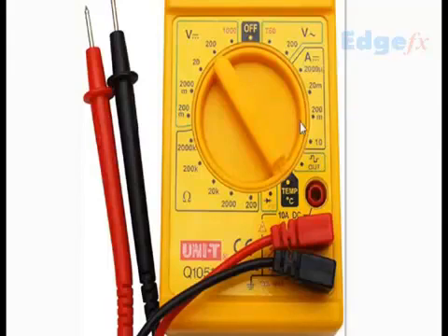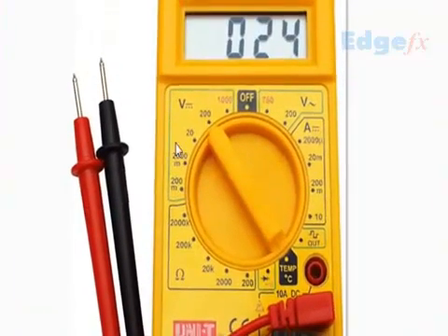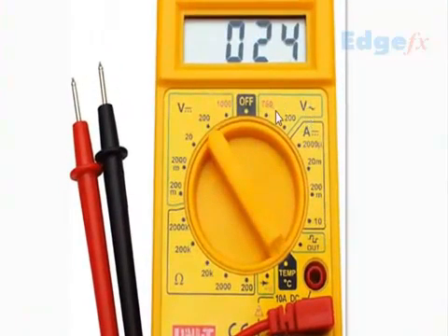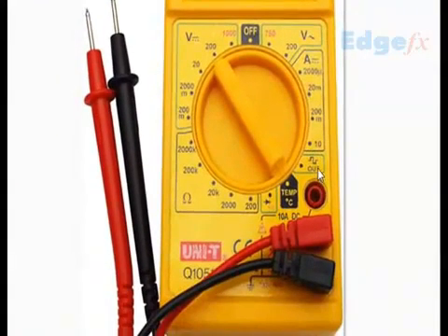This is a multimeter, and it has the provision of measuring DC voltage, AC voltage, and DC current, and some signal can also be drawn out of this. It also measures temperature with a temperature sensor, of course, and has a diode mode, a buzzer mode, and resistance. That is why it is called a multimeter. Once we take it to the buzzer mode, we can use it for the continuity test.